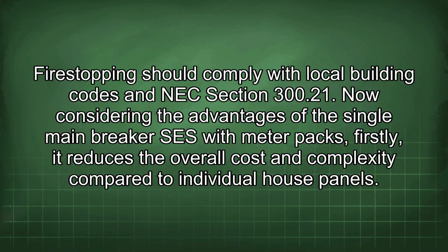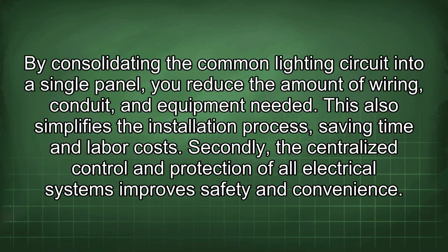Now considering the advantages of the single main breaker SES with meter packs. Firstly, it reduces the overall cost and complexity compared to individual house panels. By consolidating the common lighting circuit into a single panel, you reduce the amount of wiring, conduit, and equipment needed. This also simplifies the installation process, saving time and labor costs.